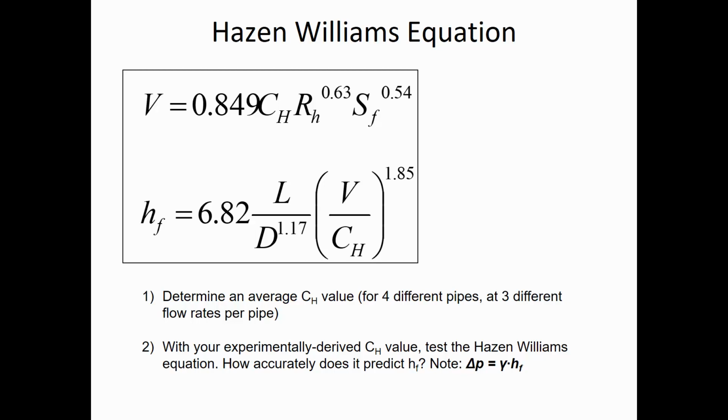It's a good equation, and it's easy to solve computationally. But then, since we are really hardcore, we always switch it to Darcy-Weisbach, because that's what hardcore people do. It's the more sophisticated equation that we'll learn next semester in 331. It's a real fancy equation, and the computer can handle it, so we bump it up a notch. But yeah, I'm glad that you remembered that this is built into WaterGEMS as one of the options.